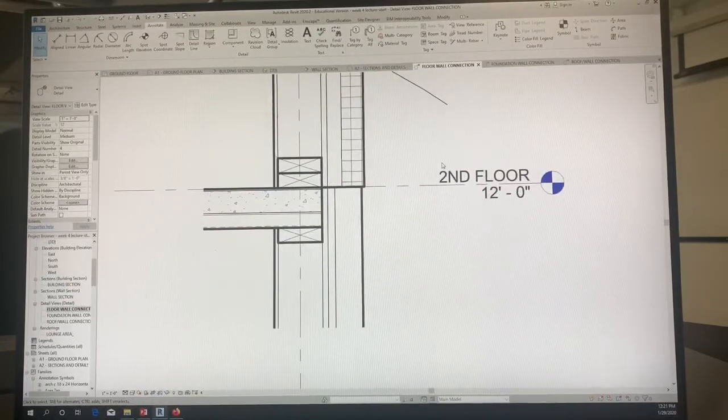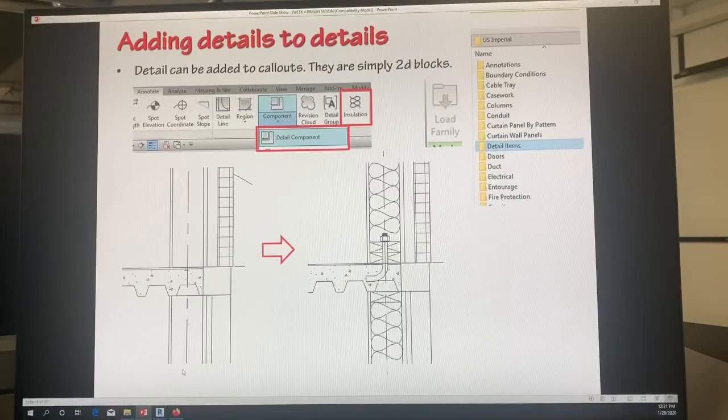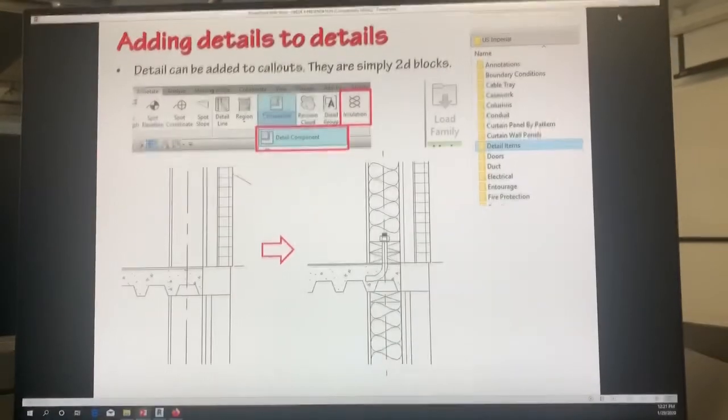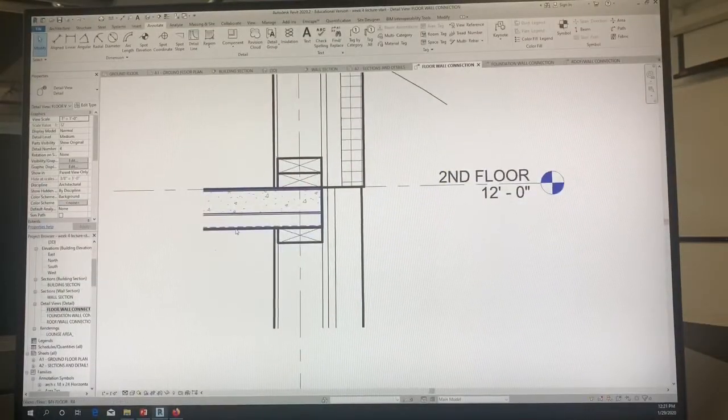Anchor bolt here. Now, before we put that anchor bolt in, one thing I did notice: look at this drawing compared to the one we have. Do you notice how I could see the metal decking in my drawing? But in your drawing, the metal decking is in the other direction. The metal decking is there, that's what this is, but it's not showing the metal decking because the span is in the opposite direction.